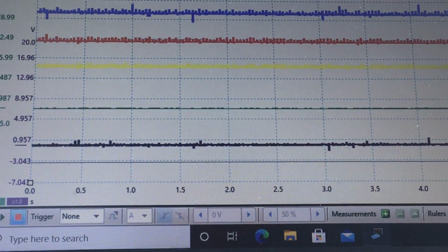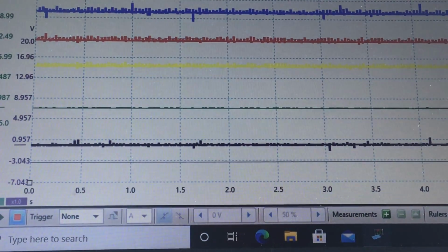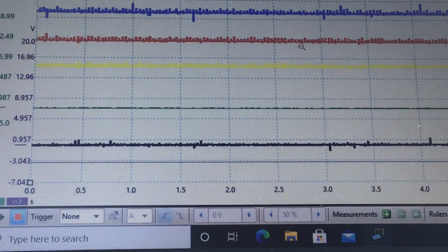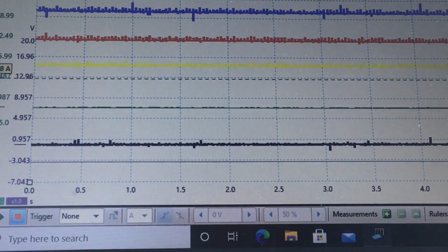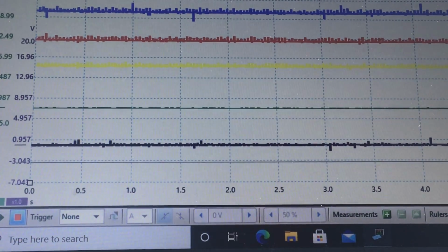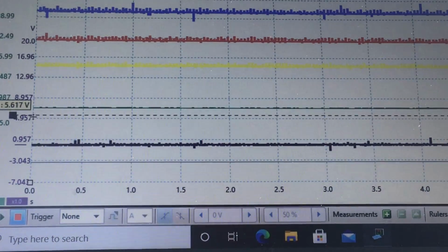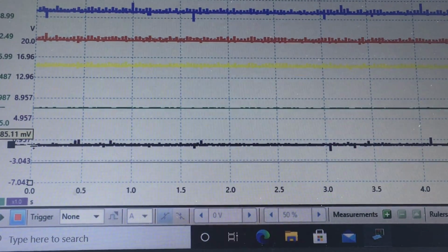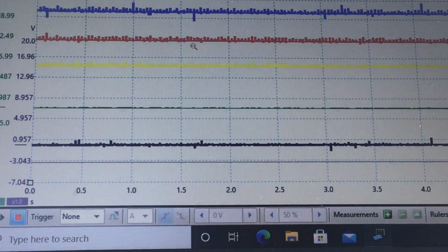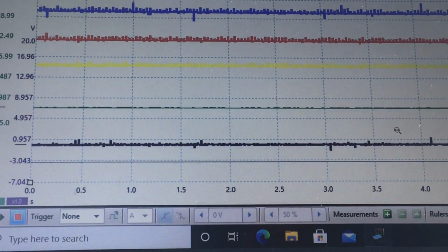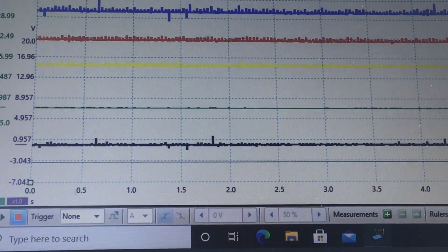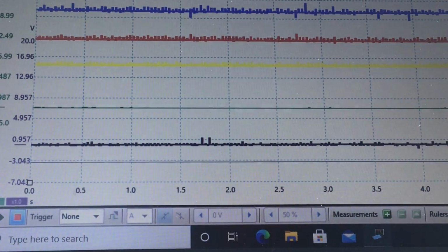The HVAC module has to know what the voltage drop is across the power transistor. Our current is not flowing. We pretty much have an open circuit. We have no current. Purple is our controlled input to the blower power transistor, and it is very low. There is nothing going in. And gray is our voltage drop across the ground of the power transistor, which is pretty much non-existent. I will go through the captures to see where I turned the blower motor on, and you'll start to see some action.